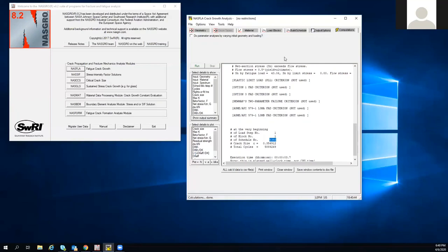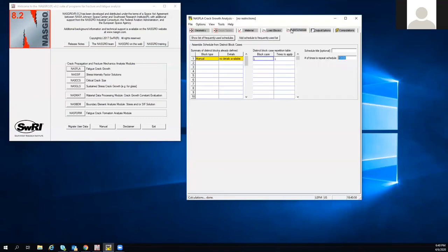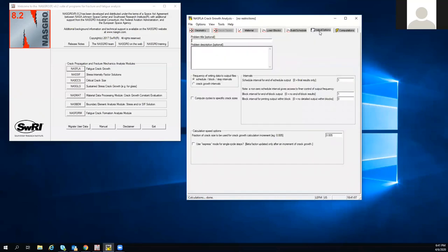So that's an interesting point. I've seen multiple industries treat it somewhat differently. In general, the scatter factor typically says something like you must demonstrate that your part can survive X number of service lives. Maybe it's 2 service lives, maybe it's 4, maybe it's 10, maybe it's a somewhat larger number.